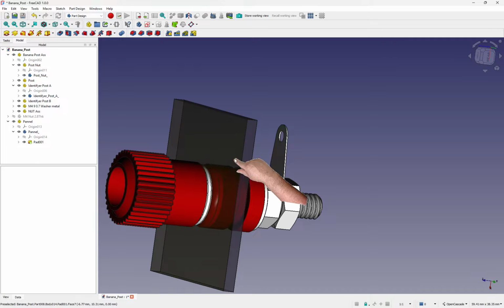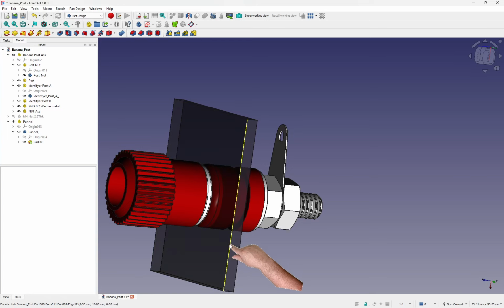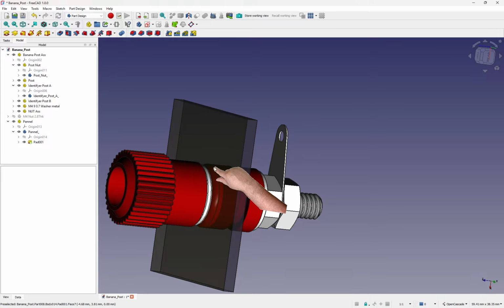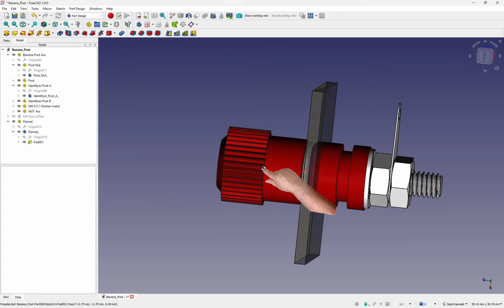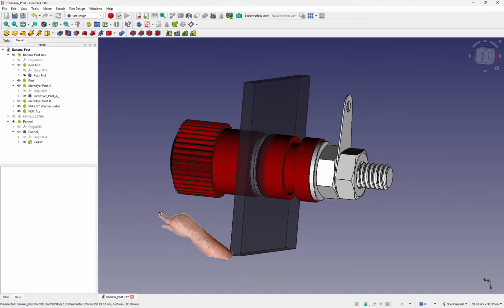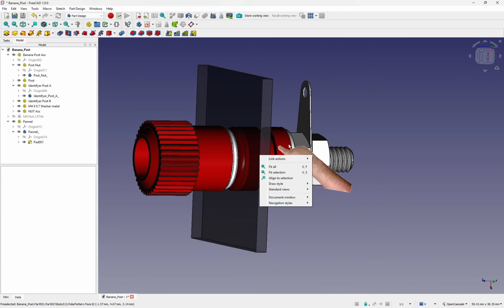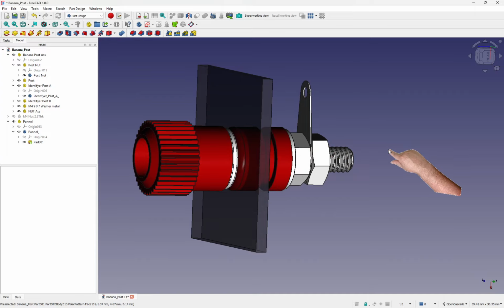Because what I'm going to have is a really thick trace, whatever, on this. So this actually connects to the PCB track, because I want as little resistance as possible. Because if you remember, we were measuring low resistance resistors in this little project, so any resistance there is going to affect our reading. So I'm going to have this as a nice, really thick track to our current source. Yeah, that's right. So there's no resistance in the current going to the actual component under test.